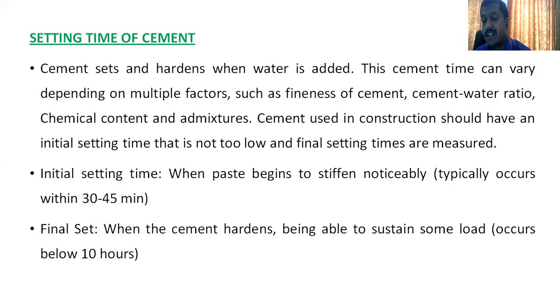Setting time of cement. Once you add the water to the cement, your observation is that the cement starts hardening. That paste will start hardening. Now this concept is very important for us. There is the start of hardening of the cement, and there is the point when the cement paste gets hardened completely. It is important for us to know these values.